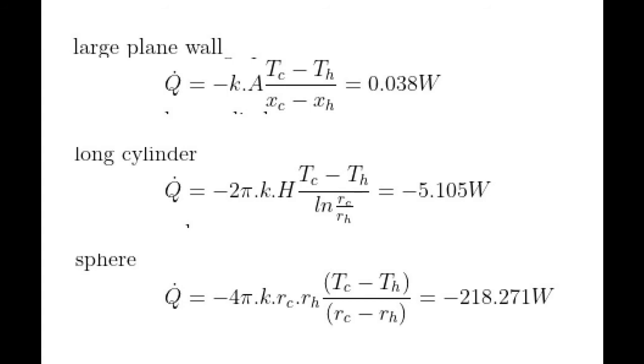If we look at the derivation of the rate equation for sphere, integration of the Fourier law of conduction involved the whole surface. This means we need to do an additional step, so that we can make appropriate comparison with values calculated for long cylinder and plane wall. This involves calculation of the heat flux, and the rate of heat transfer, when the heat transfer area is only 1 times 1 millimeter square.